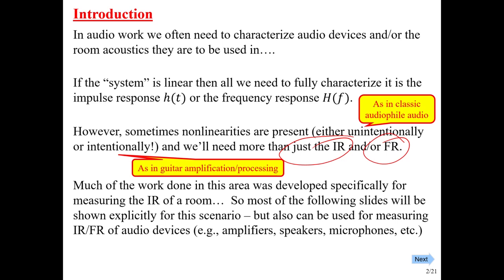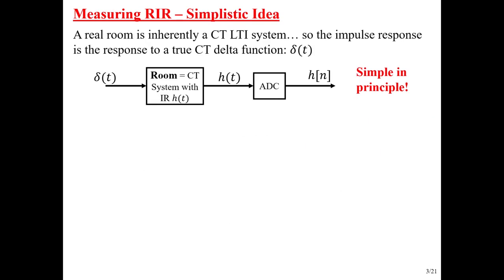So if we're using a speaker to send a signal into the room, and then a microphone to pick the signal up, if we're trying to measure the impulse response of the room, those things could have some nonlinearities in them, and that could cause us problems. So we'll see how to get around that as well.